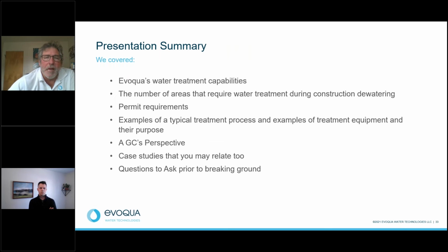You may get into sites where it's very clay rich, very silt rich, and you may just get maybe a couple thousand gallons of water in the hole during the day. You could pump that off into a weir tank or frac tank and just hold it for days, and then put a very temporary treatment system on it to batch treat it whenever you need it.